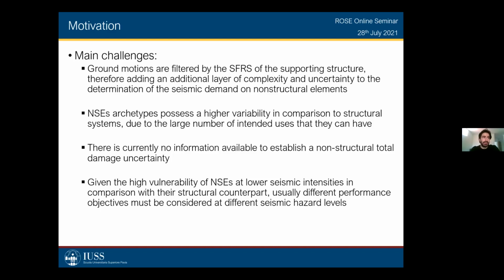This is not the case for structures usually, because, for example, the FEMA P695 basically assesses the performance of the structure just against collapse. So they just care about the collapse. And that is basically the main criterion you use to assess performance. When you're talking about non-structural elements, we cannot do this because there are a lot of different limit states that need to be checked, given the high vulnerability that these systems have at different seismic intensities. So usually this requires that different seismic hazard levels must be considered.